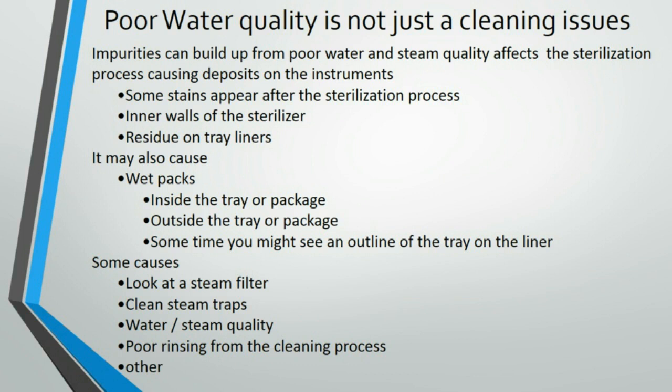So poor water quality isn't just a cleaning issue. Impurities can build up from poor water, and steam quality affects the sterilization process, causing deposits on your instruments. So some stains appear after the sterilization process, and I'm going to show a couple of pictures of some things that do not look so great because of what's coming out of the steam. Inner walls of your sterilizers can not look so great as well. If you're having water issues and you don't have them cleaned regularly, you can have some pretty ugly looking internal walls of your sterilizers. And then it can leave residues on tray liners as well if that's something that you use.